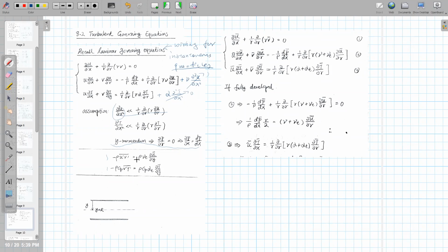What I say, additional Reynolds stress terms, u prime, v prime here, similar to what we have in our external turbulent boundary layer cases. You will also have the Reynolds stress for the temperature fluctuation term. And again, you define the eddy viscosity and thermal eddy diffusivity, mu_T and alpha_T here. And you do the averaging on the three terms. So this will be the final.